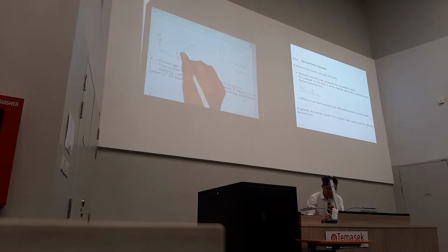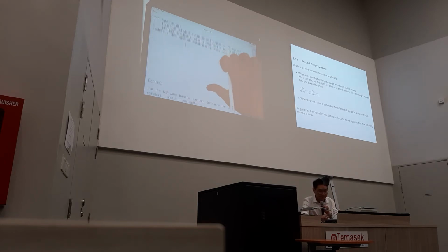And this format is very important. Just like the first order transfer function, K divided by tau s plus 1, for second order you also need to understand this format. So from here, if I ask you what is the damping coefficient, I give you a second order question. You need to rearrange it in this format, compare each of these coefficients and find the final value. That is the main thing that you need to learn from this second order system. Okay, I'll give you an example.